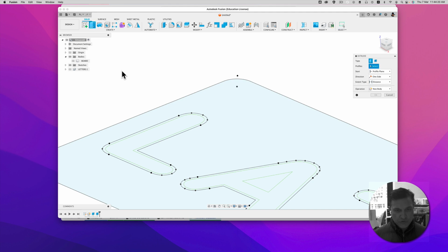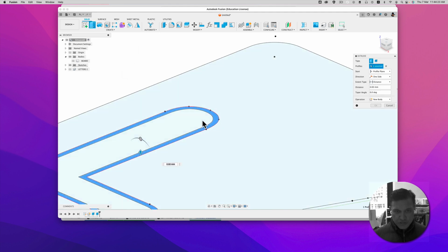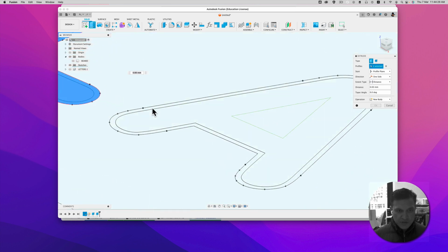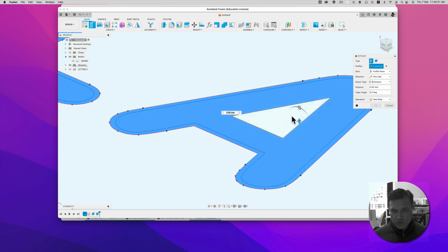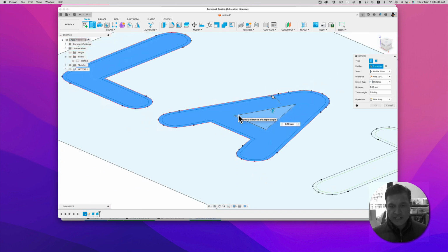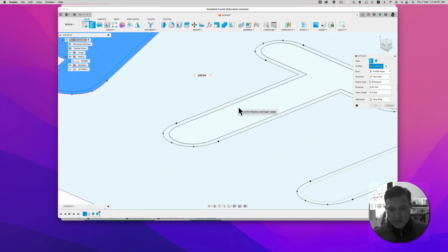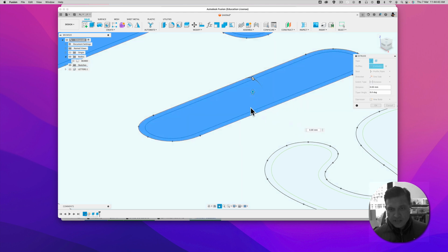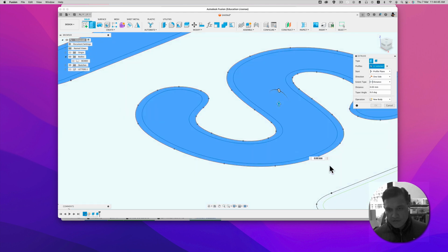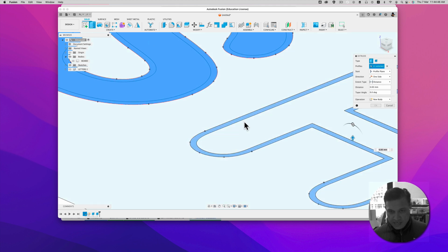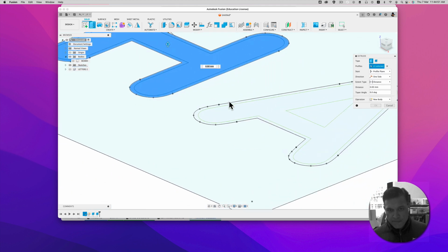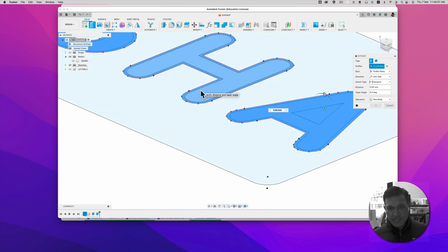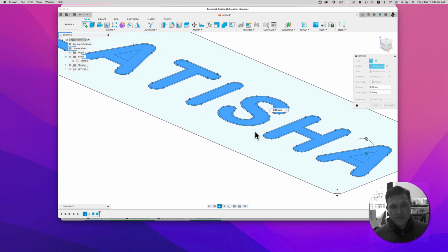I'm going to press extrude, and this time I'm going to touch both the offset of the letter and the letter, except in this case for the letter A, I also want to include what we call the island of the letter, and you'll see why in a moment. So I'm then just moving in, and here I'm panning as I'm zoomed in. It's the mouse button 3, press straight down. Very fast to do this. And I'm just zooming in and out and panning, being careful to select the areas that I need. So there they are, the offsets included.